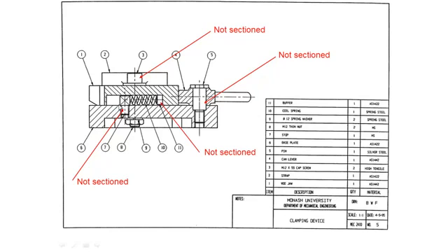So that little cross is just a little detail you might want to note when drawing, and that's in your drawing handbook. We also haven't sectioned our spring here, as from sectioning it we would gain no extra detail, and sectioning it's just tedious extra work.